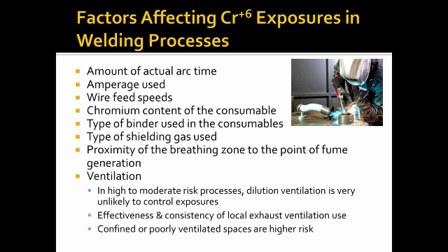Abrasive processes are the last category that I'll talk about here. Oxidation to hex chrome from elemental chrome that's in a metal, or even trivalent, is not likely to occur in grinding and blasting operations. So my experience, as well as that of others, is that the exposures tend to be low for hexavalent chrome. It's not to say that you won't find a lot of chrome in these samples. It's just that it's not necessarily in the hexavalent form.